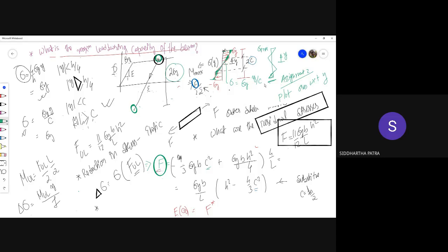So residual compressive stress is a reality, and residual compressive stress is of great significance. We need that. By incorporation of the residual compressive stress, they take the stress state locked. Even after the balls have hit the weldment and left the region, the stress state there would still be compressive, because in some other location it would be tensile.